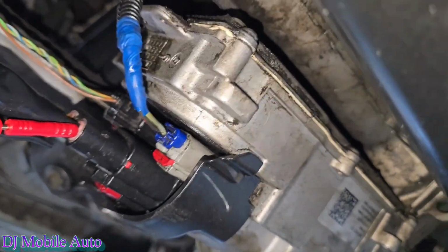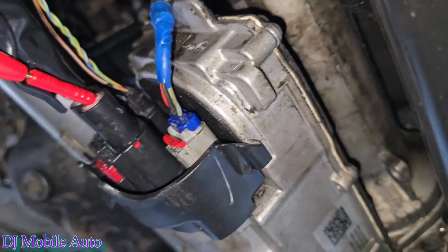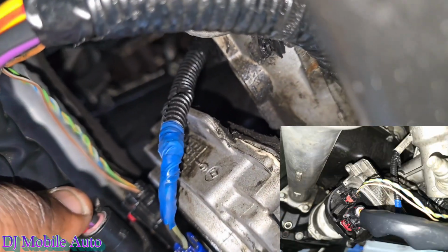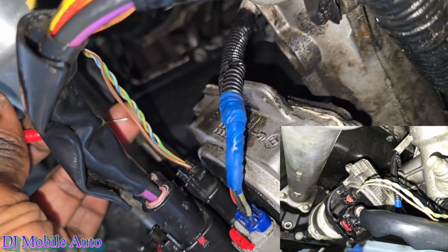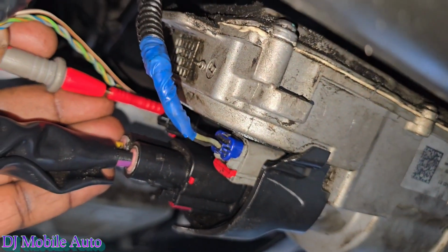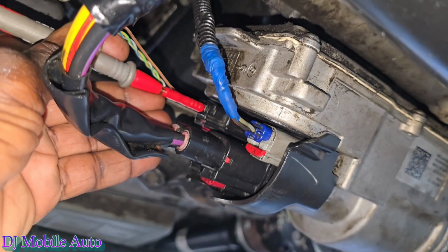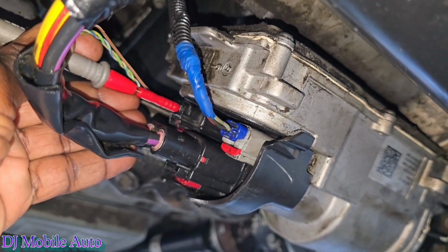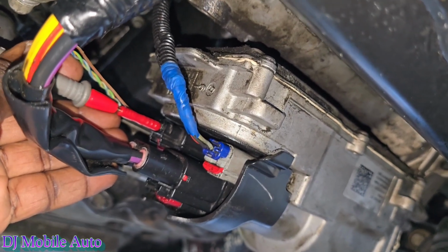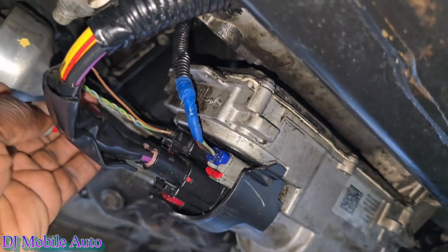Okay, so the next, these are the sensors that's coming off the rack, right? So what I gotta do next is check for the communication lines, which is these 2 wires that's crisscross. Okay, so I'm getting battery voltage off this brown wire with the white stripe. So that's coming from the fuse number 19, which is a 10 amp fuse, right? With the key on and the engine off, or even if the engine was running, I'm supposed to get 12 volts. So that's letting me know that the module is getting power, and you saw that also on the scan tool.